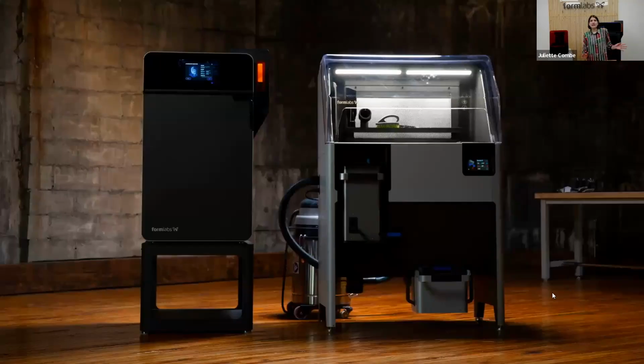So that was for SLA. Now I will talk about SLS. While SLA is resin-based, SLS is powder-based. So it uses a laser to fuse powder particles together. And one of the great aspects of SLS is that while the part is being shaped, it is actually held in the powder bed. So you actually don't need to use any support when you print, while you need to use support with SLA. So this technology is really great for producing very complex parts, complex shapes.